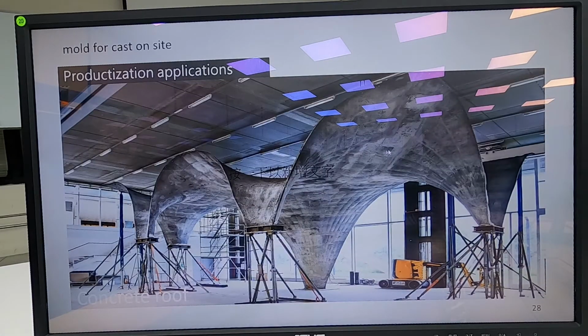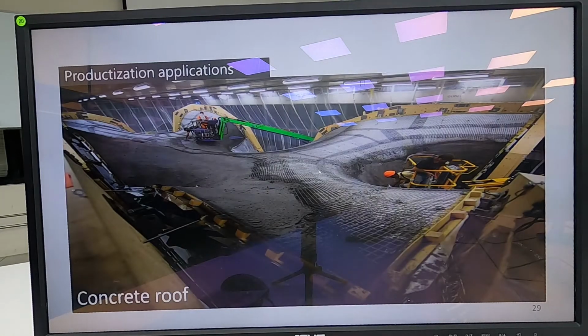And this is a possibility where you have a laminar strip as the backbone, and then you put on the membrane, and then you spread on the concrete, and it becomes a structure like this. Some of you may have seen this one. It's a project from another university. They put all the textile membrane and tension it, and then spray on the lightweight foam concrete and make it cure, and then it can support itself. So you see, this is a laminar strip structure.